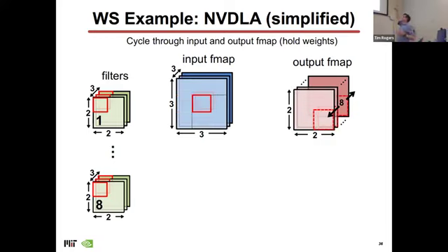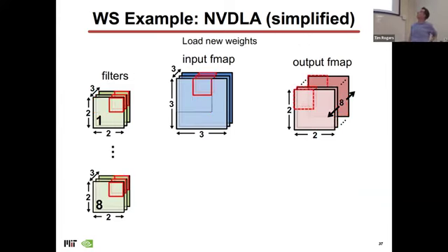And that corresponds to these outputs in the output F map. And of course, those are partial, right? It's not done. So then it has to send those partials down to the next processing element that's dealing with the next filter element, right? That way it carries on, and you can chain these things together like that.